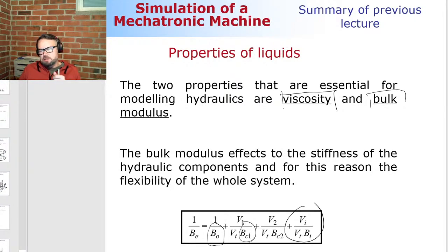First of all, it makes the system vulnerable to cavitation. So cavitation can take place in certain components, and then it lowers the flexibility. And as a rule of thumb, we would like to make everything, mechanical components, hydraulic actuators, and so forth, as rigid as possible.